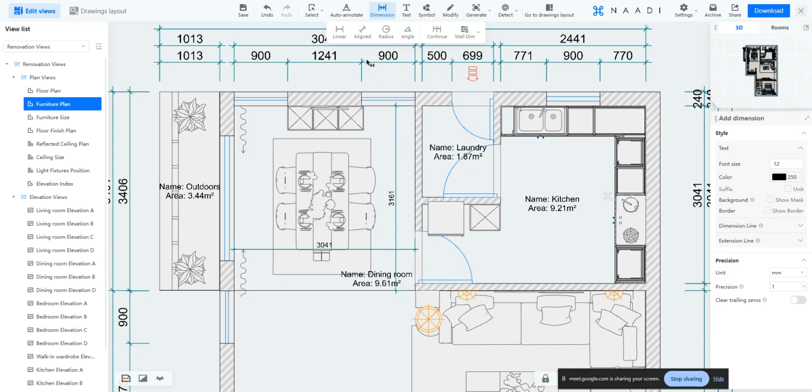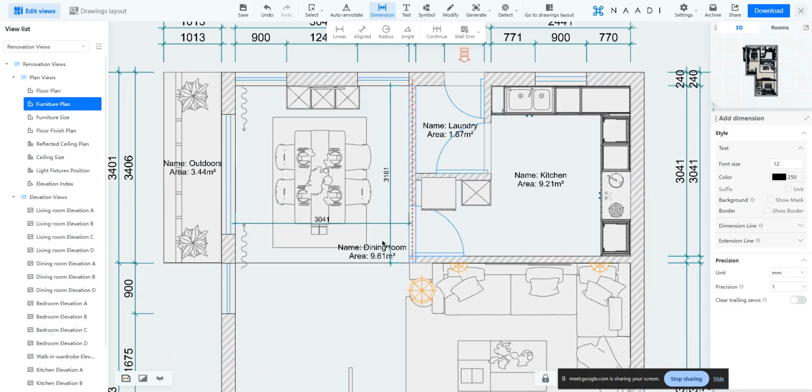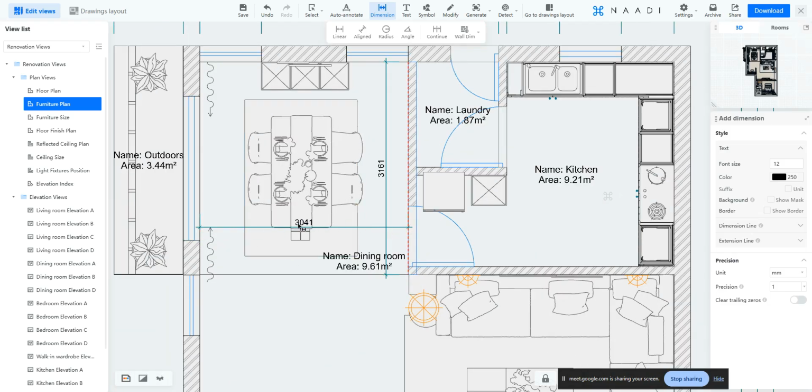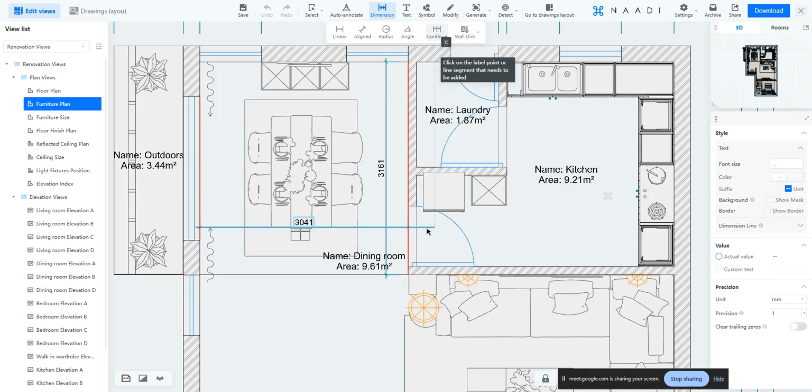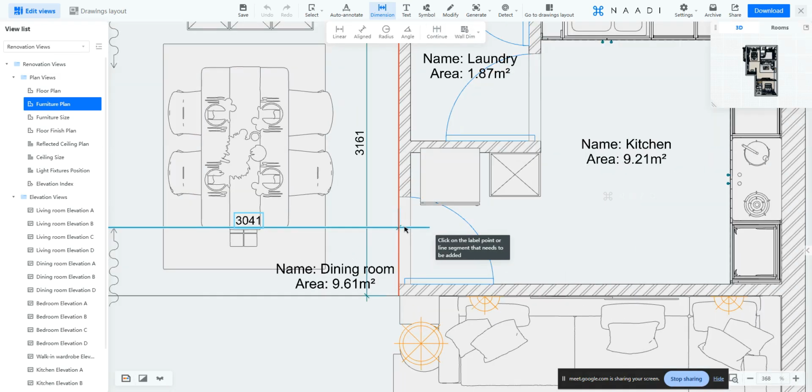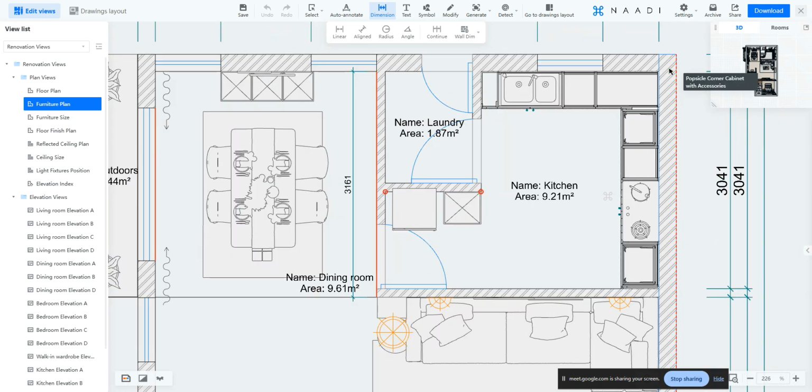And here, like I said, what this dimension continuous will do is, once you draw a dimension and set it at a point, just click on dimension continuous and that last dimension will be continued. Can you see? I'm literally continuing where I set my last dimension, and I can just keep on adding multiple dimensions here. And the best part is all the dimensions which I'm adding will be aligned at the same level. That is technically what DCO will do, right?